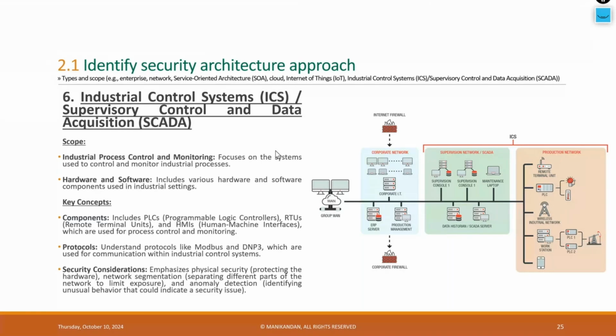Now, what is the primary risk factor of SCADA? The primary risk factor is that SCADA doesn't have any security functionality embedded in it. They either use the DNP3 protocol or Modbus, and the problem with both protocols is that they don't provide encryption. So when we are planning to use SCADA devices in our organization, we have to make sure they are physically isolated from your TCP/IP network. In a nutshell, your SCADA devices should be air gapped.